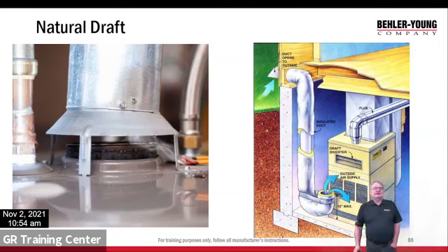Again, I'll look at matches around a draft diverter on a water heater, and you can see the smoke being drawn up there. That's a properly functioning chimney. Somebody did their work right.